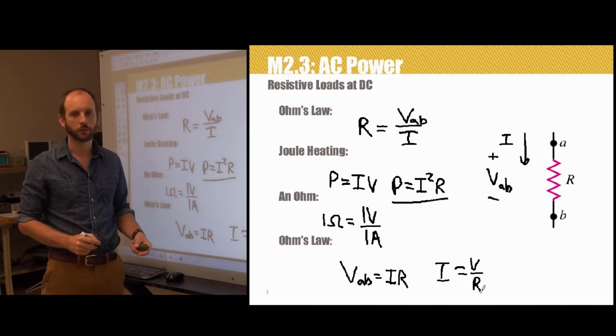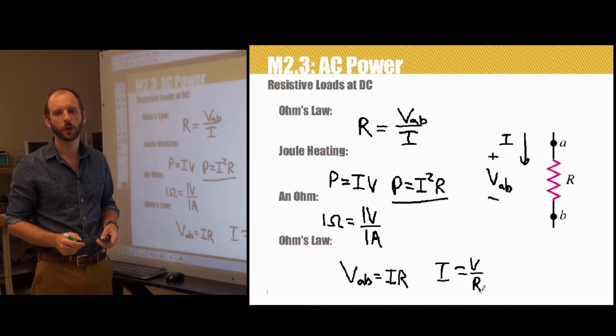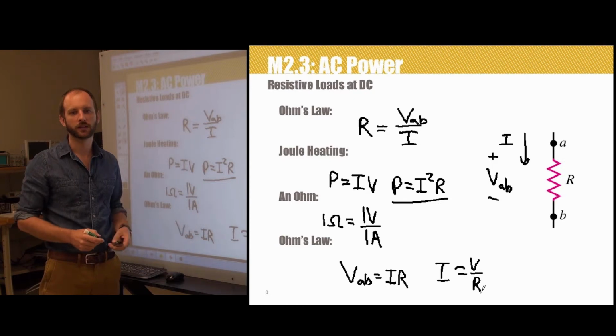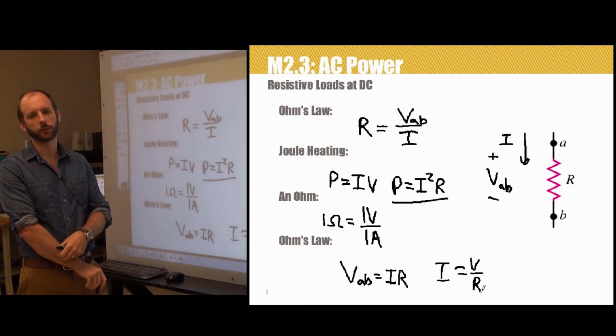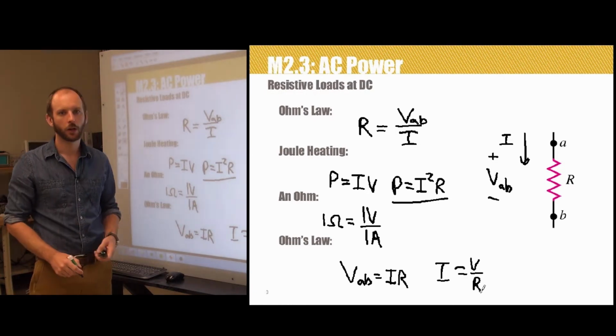So these again are done for the purpose of circuit analysis because usually the value of resistance in the circuit is already known. Using these formulas we can reference the current through the resistor to the voltage at the terminals of the resistor, and it's become standard to say that current enters the positive terminal of a resistor and produces a voltage drop across the terminals of the resistor.